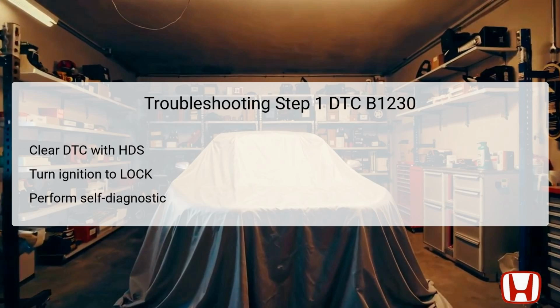The first step in troubleshooting DTC B1230 is to clear the Diagnostic Trouble Code (DTC) using the HDS or Honda Diagnostic System. This process resets the vehicle's computer, allowing the system to begin fresh and recheck for any current errors. Next, turn the ignition switch to the lock 0 position, then back to the on I position. This activation can reinitialize the vehicle's electronic systems and may resolve minor glitches.